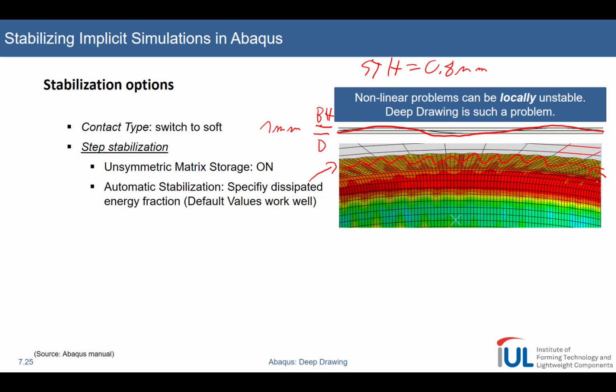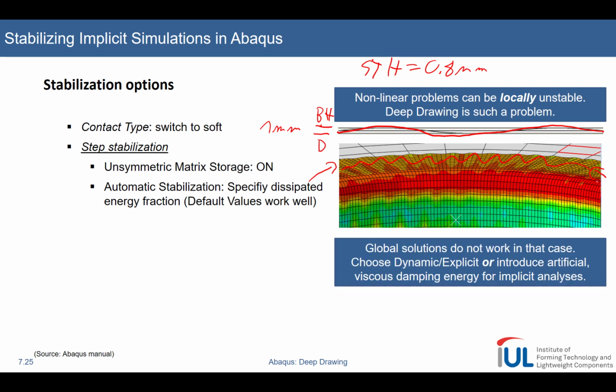So at a very early stage of your simulation, your Abaqus Standard won't find a solution anymore, because this waviness pattern is caused at a very early stage in your simulation. In this particular case, and this is the case for many sheet metal forming operations, I know you could also circumvent this using maybe a specially adapted blank holder force approach, so applying a Neumann boundary condition so that you don't see this waviness emerging, so that you prevent this buckling problem.